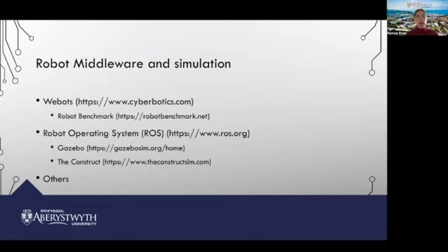But when we have a robot middleware, the middleware itself will provide a level of what we call abstraction away from the physical hardware, which means that we can take a single program and apply it to lots of different robots. So any robot that has wheels and is able to drive around, you could take the same program and it would work very similarly on each of those robots without having to modify your code. That significantly increases the reuse and the ability to share programs with one another.